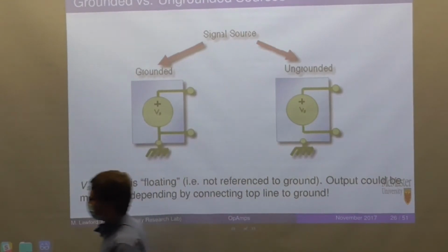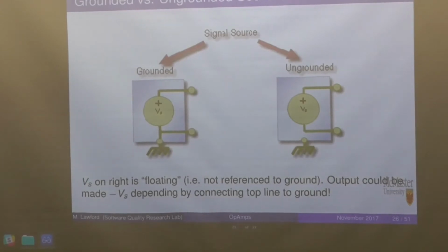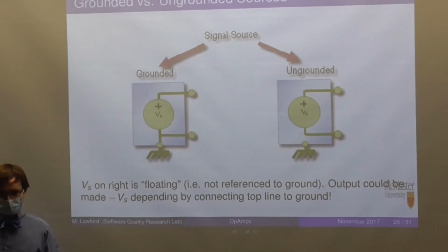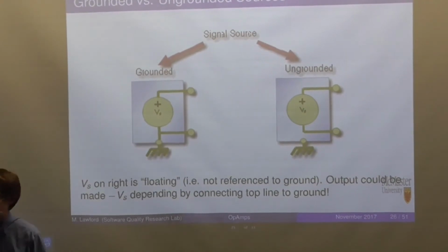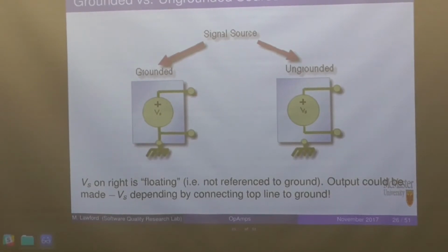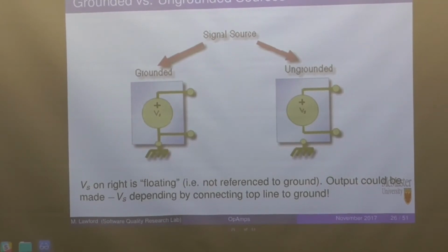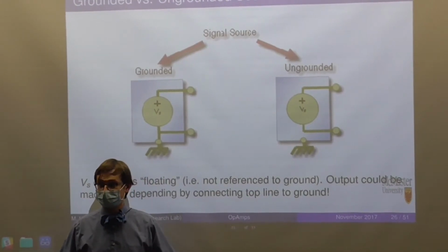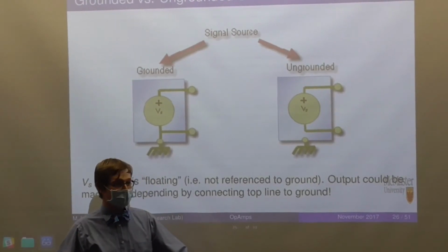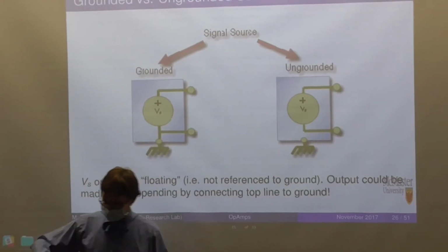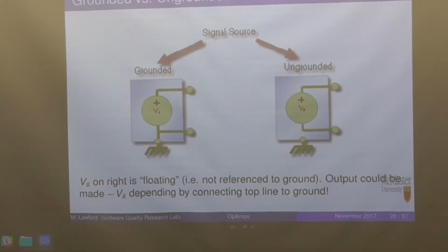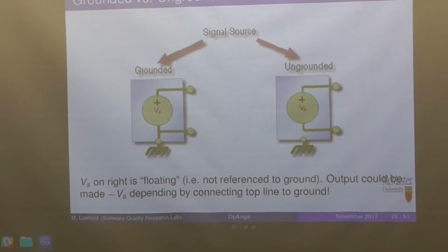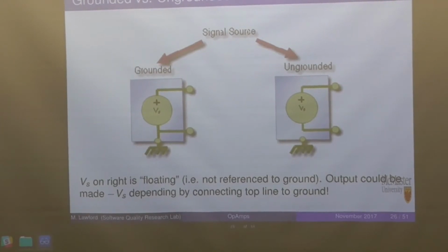It's because of ground loop interference. These things could be connected to two different things that have a potential difference across them, so the grounds do not agree on what 0 volts is. That can lead to electrical interference and problems. It might even be damaging to your system if it gets out of hand, because sensitive electronics be sensitive. But anyway,